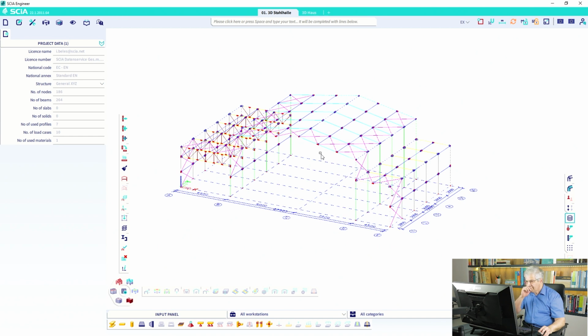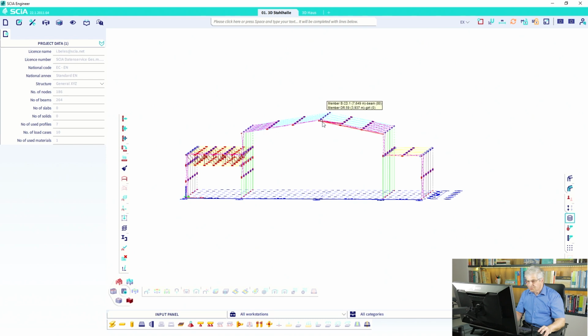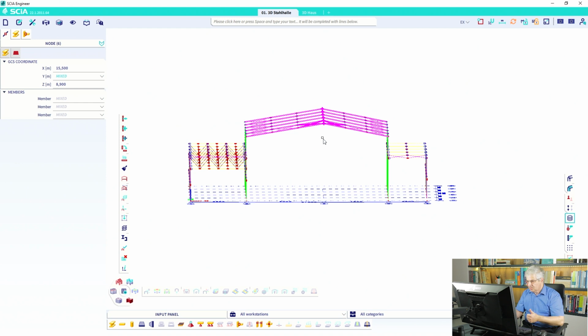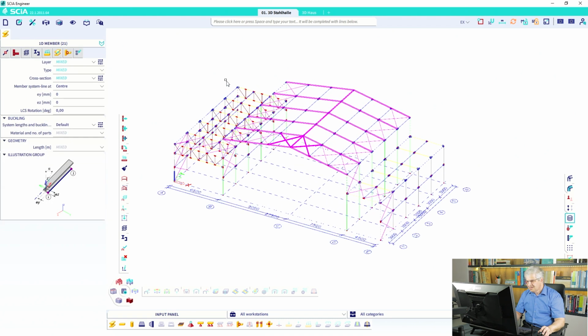And I would like to select only, for example, 1D objects, or only nodes. So I go here and select a window. So I have in the selection members, maybe load panels and everything else that I don't need. I need only nodes, or only these 1D members, and I don't want to have the hinges here. What you can do, you can move them to the right. You can move them also to the right. And then we have selected, it's not so well visible.